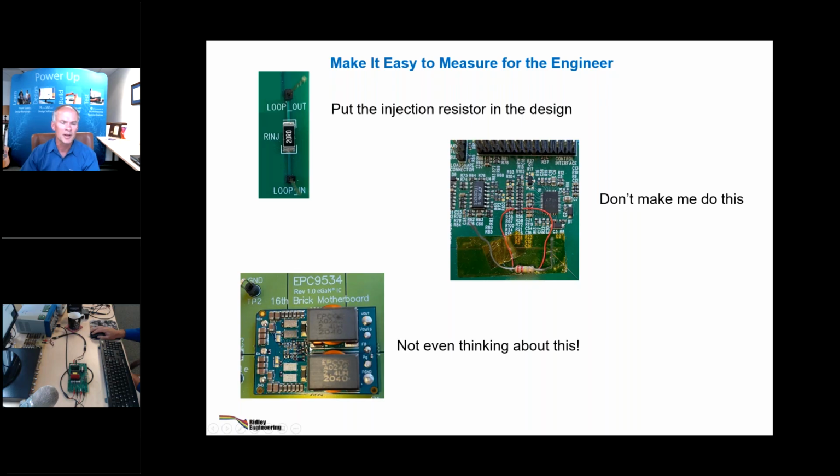Here's the latest board from EPC. I don't even know what size these parts are there, but I'm just not going to go there. Okay, I can't. It's a sixteenth-brick motherboard. I'd love to know what the loop is, but I can't look at it. If you're going to add your own load capacitance, you've got to be able to measure and look at what happened with the load that you're going to use, and then measure that loop. But it's getting buried. So on the one hand, in the industry, we've got this awareness that we'd better always measure this loop. On the other hand, we're going to make it more and more difficult for you to measure the loop. So they just don't go hand in hand with each other. All right, enough. I think everybody got the point on that. If you have any app note people, just give us a